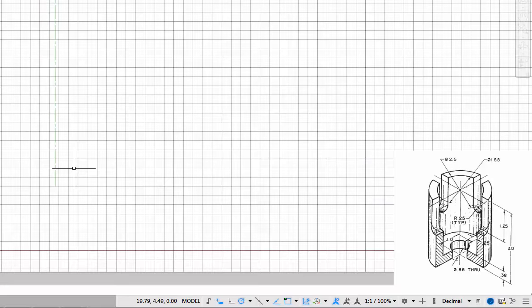A full section is an object cut in half. A half section is an object cut in 1/4. I know it's kind of odd, but that's the structure and how it works. It actually does make sense. Full meaning a full half cut through an object. Half meaning half of that full cut. So if you think about it that way, it does actually make sense.